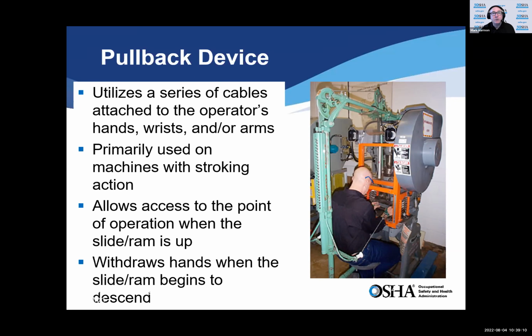I would only caution you that if that is the type of machine you have, please make sure that those pullbacks are adjusted properly. Because if you can imagine, not everyone has the same body shape, style, and length. And so if you put these pullbacks on, and somebody at the end of your shift puts them on, if they have longer arms, they're going to be able to reach further. So the pullbacks have a very specific adjustment requirement.